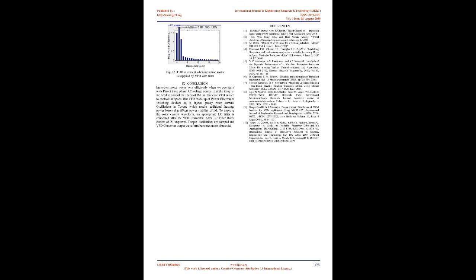To improve the rotor current waveform, an appropriate LC filter is connected after the VFD converter. After the LC filter, the rotor current of the IM improves. Torque oscillations are damped and the VFD converter output waveform becomes more sinusoidal.